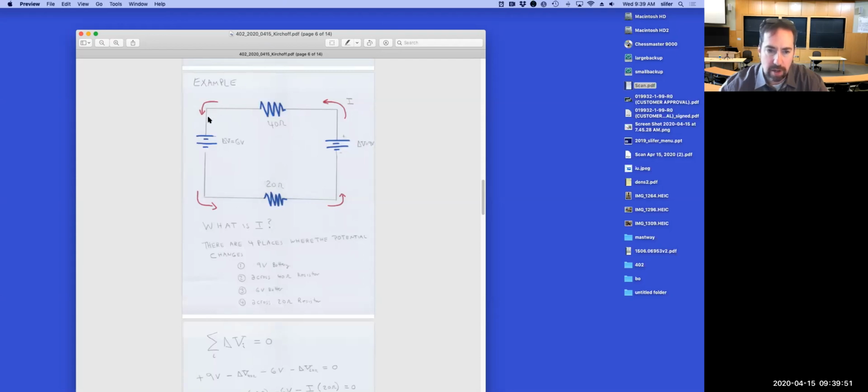And then I'm going the wrong way through this battery. I'm driving the wrong way down this battery street. It's going in the positive terminal and out the negative terminal. Because of that, we want to make this a negative 6 volts. We don't count that as a positive 6 because this current flow is going in the wrong, or unusual, direction. And then we have a potential drop across this resistor, and for the same reason as for the other resistor, that's going to be negative. So I signify that with a 20 ohm subscript there.